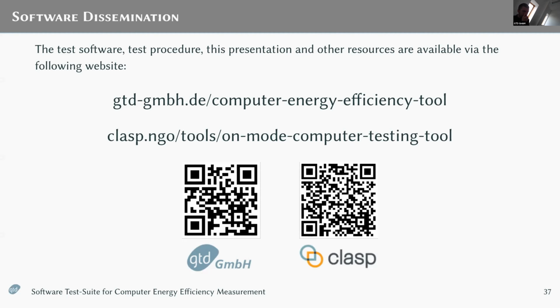One thing that I wanted to add there is that we make an a priori synchronization before the test. So afterwards, we don't need any heartbeat type of synchronization between the controller and the equipment under test. We synchronize the clocks first, and then you start measuring.